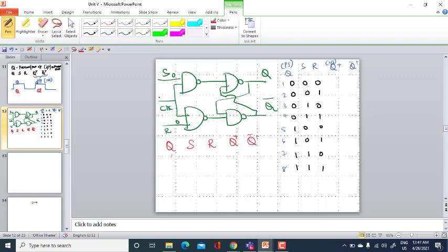And we know this is your clock and this is positive level triggered clock. Consider this is always 1. So whenever we have the NAND gate, whenever one of the input is 0, output is 1. So here also 0 1, output is 1. Here one of the input is 1 and another input of this gate is also 1. So this gate let us name it as 1, 2, 3 and 4.